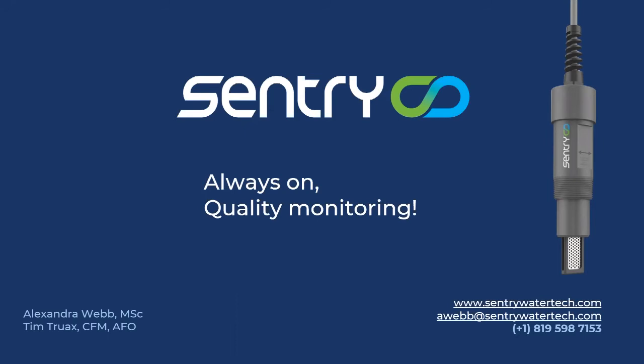So we moved that to the effluent launder of the primary clarifier, and because we have extremely low flows during early morning hours, I actually backed up the effluent launder using cinder blocks, which I secured so they didn't end up in my aeration tank. And that change in location gave a more steady signal for making decisions based on what was entering the aeration tank.